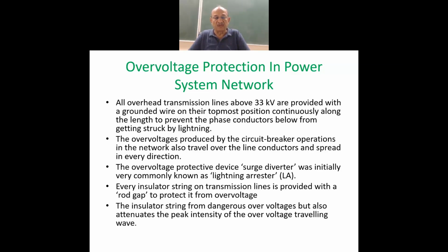At that time, the transient overvoltage which played an important role was the lightning impulse, the external source of transient overvoltage, because the switching overvoltage magnitude depends upon the rated voltage, that is 2 to 3 or even 3.3 per unit is the level of switching overvoltages.